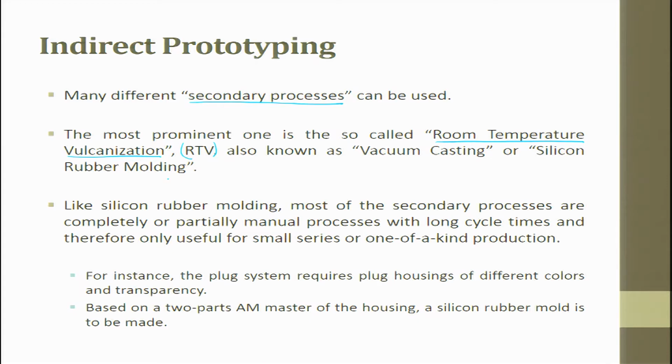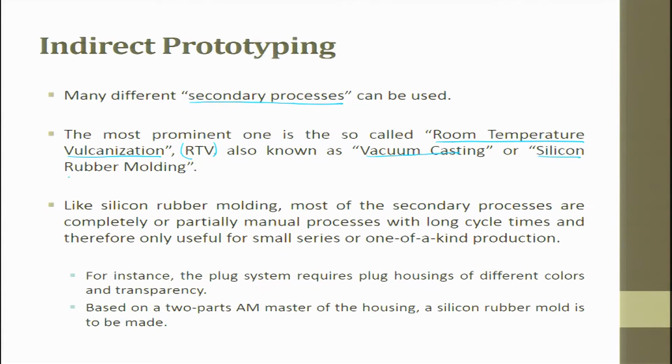In the introductory lecture, I was talking to you about the ear which we made for the left side. We did the right side scanning of the ear, and then we did some tweaking with the help of the doctors. Then we tried to make a mold by rapid prototyping, and we used this technique called vacuum casting or silicon rubber molding to get the output we wanted. So, that is nothing but indirect type prototyping. In fact, it is indirect type manufacturing itself that we did.